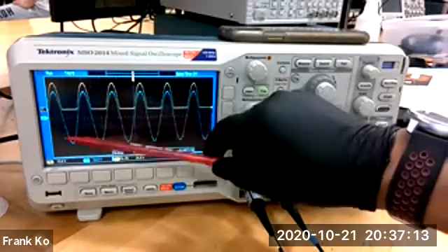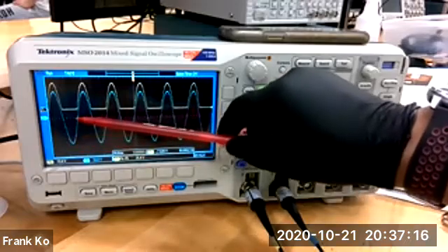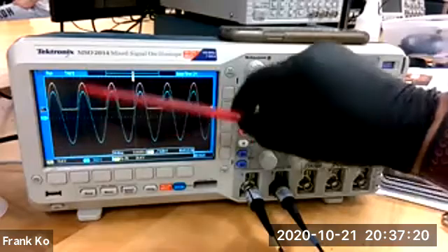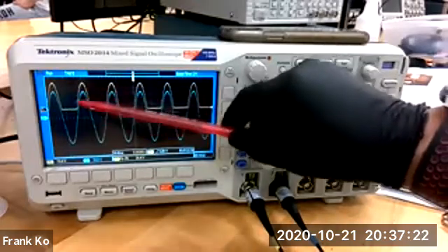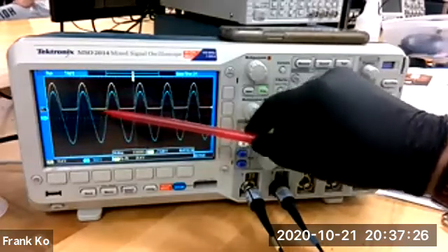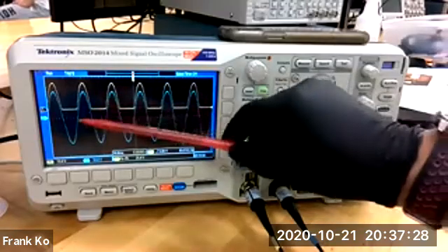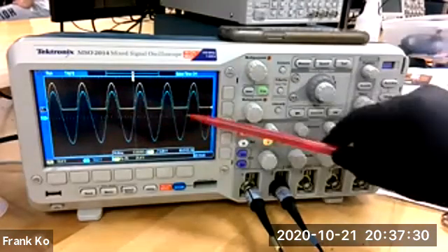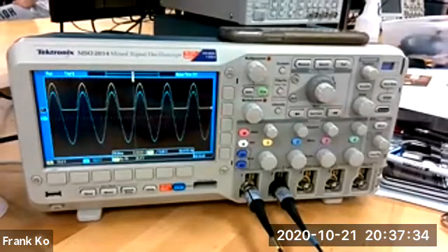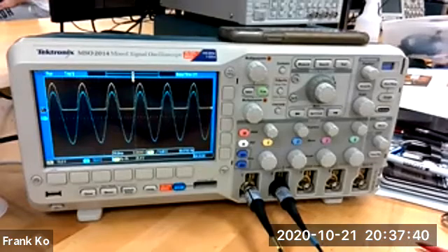We're not using the negative half cycle of the input because there will be nothing that happens there. And we're using the positive half cycle again to give us positive output. We're not using the negative half cycle, so that gives us nothing here. So we're only using half of the input waveform in order to get an output. Does everybody have a better appreciation why this is called a half wave rectifier? Are you able to get this display on your screens?